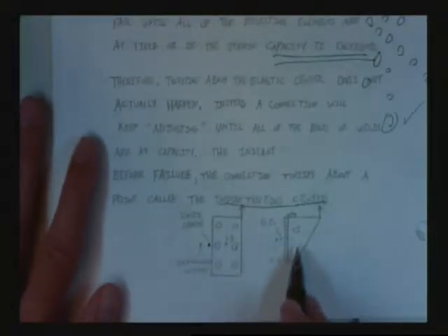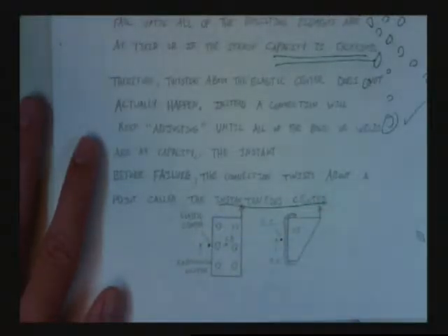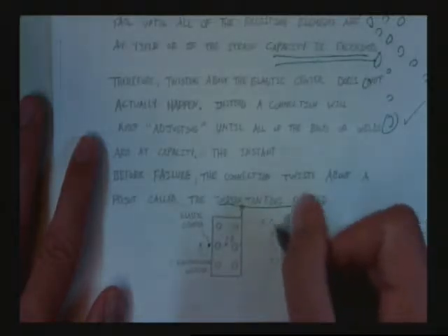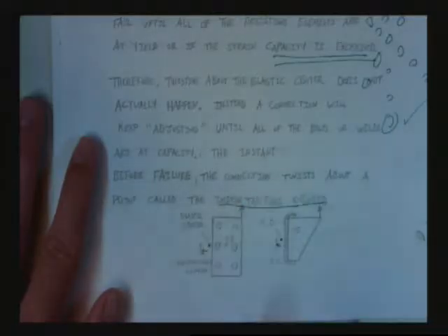Same thing here for this weld. Believe it or not, your elastic center of twist is going to look something like that, and your instantaneous center is actually going to be even further outside. Now, depending on how long your legs are, your elastic center of twist may be here. It may move around in here. The point of the story is that they will move in this direction. These are for symmetric connections. For unsymmetric connections, they can move in odd ways.